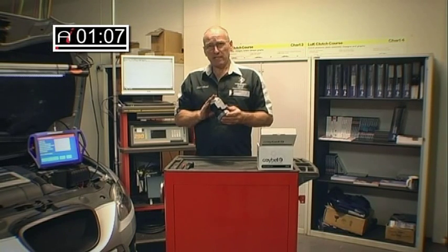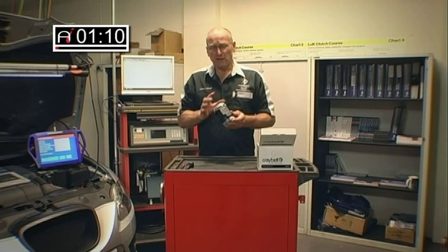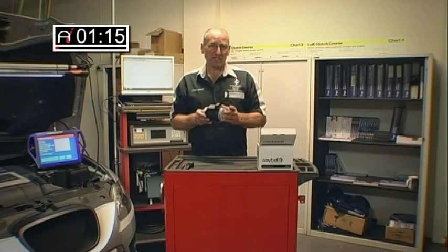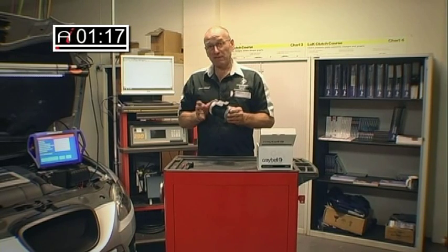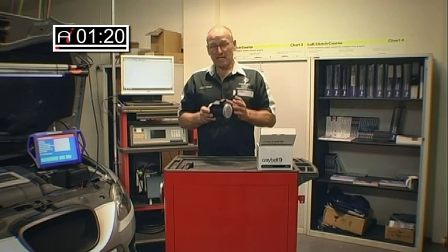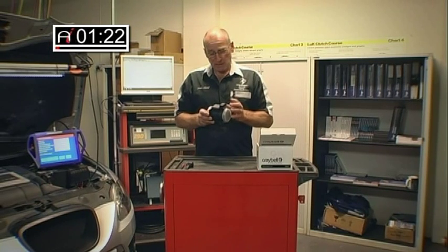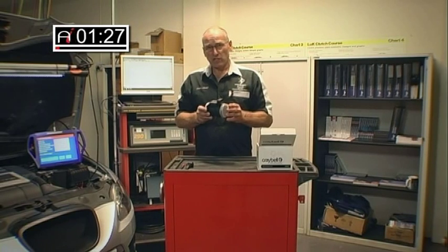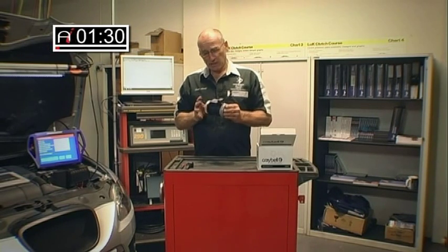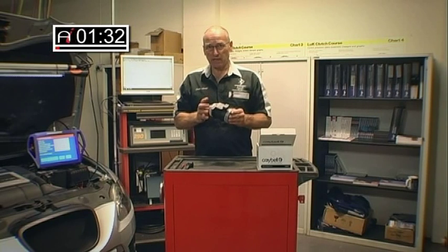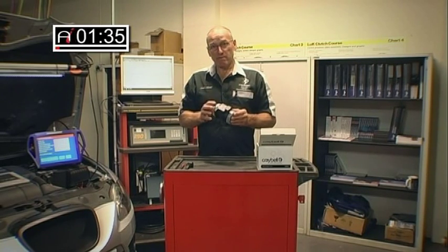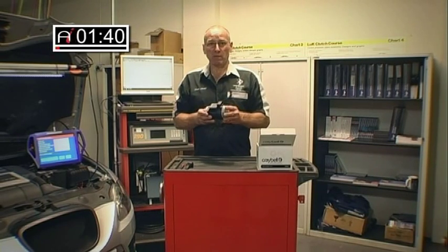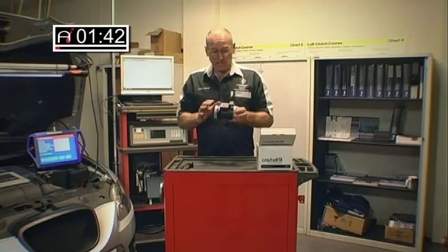Air mass meters now come in basically two variants, analog or digital. The trend now, of course, is to go entirely to digital air mass meters, and indeed the vehicle we're using today for this presentation has a digital air mass meter, because I'd also like to demonstrate how to test digital air mass meters, which differ slightly in the test process from analog, although some of the data measured is actually the same. It's measuring the mass of air, which is a calculation from the amount of air ingested across the sensor.